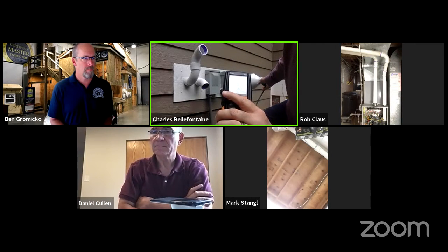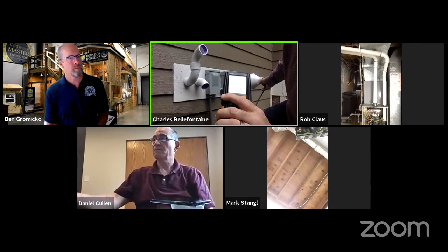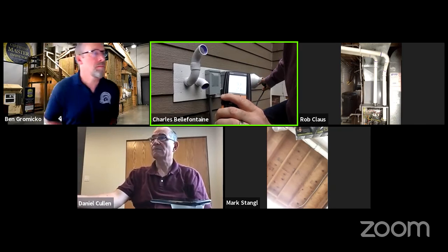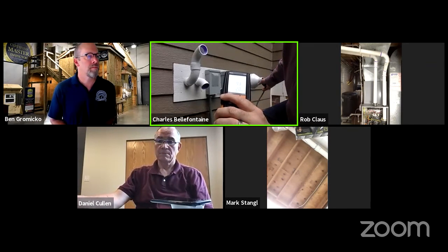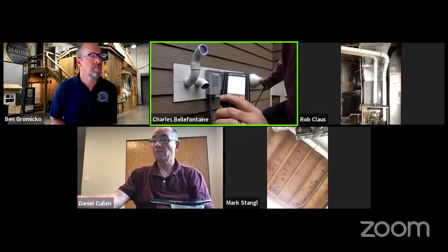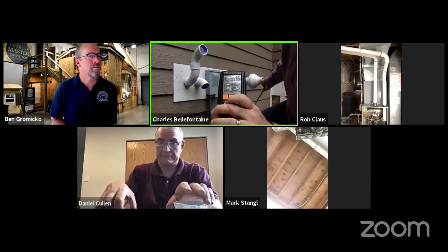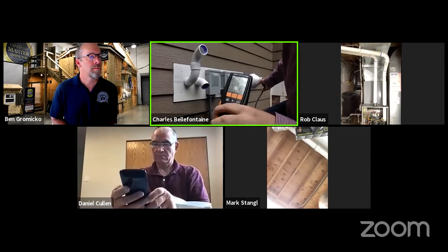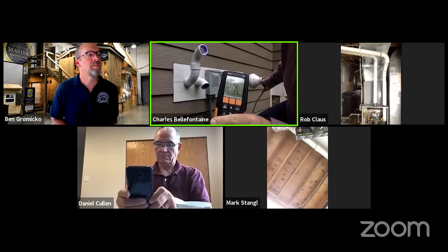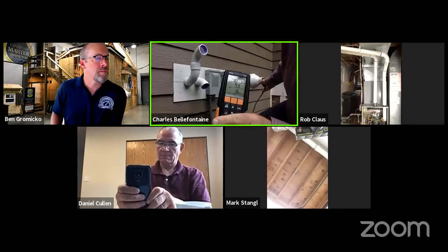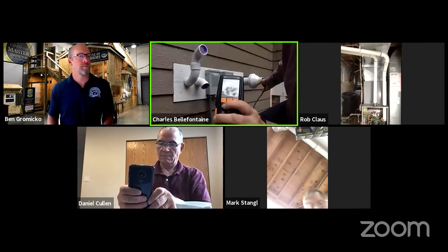I personally like it under 10, but there's nothing that I can find anywhere that proves that's what it should be. But I've seen these things tuned so well. We go with 100 as our magic number. Anytime it's over that, we're going to bring in a heating contractor, and tell them that there's a clue. So everything is a clue. There's nothing that's guaranteed. That water that I mentioned before underneath the blower fan on the floor, that's a clue or an indicator, all right?